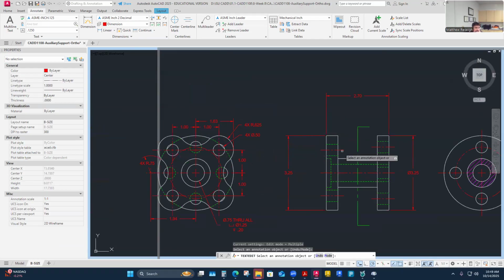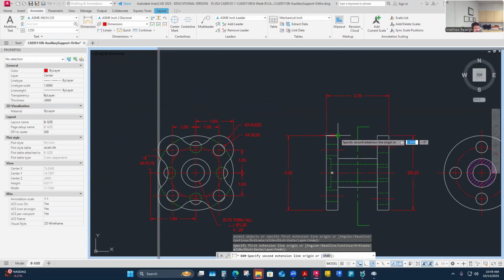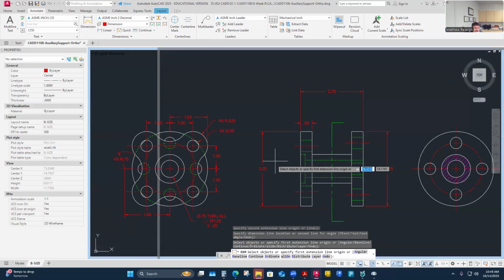That's one thing I haven't captured here though. If I go back to this plate, yes, we did great with all of its locating. When I was considering the outer profile and its dimensions, which I've got here, maybe it should have caught my attention that this dimension was needed here. And that means I'm establishing this front face as probably another control surface essentially, that I'm pulling that dimension from now and this dimension from there. So the argument could be that I would say, well,